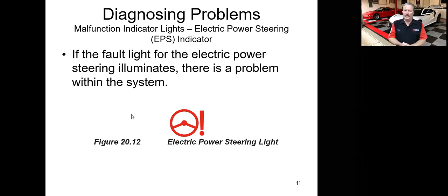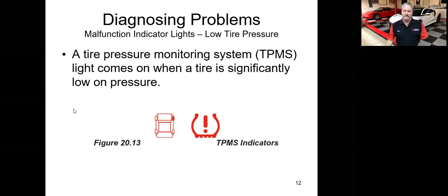One thing I want to talk about also is when we do get these codes on the vehicle, sometimes you can get 4 or 5 or 6 codes, and this is why we don't want to jump the gun and start throwing parts at cars. One code could cause a problem that's now affecting something else down the line and can trigger another problem with the way the vehicle is running, and it'll trigger another light and set another code and another code. So once again, there are proper procedures for checking these codes when they come up.